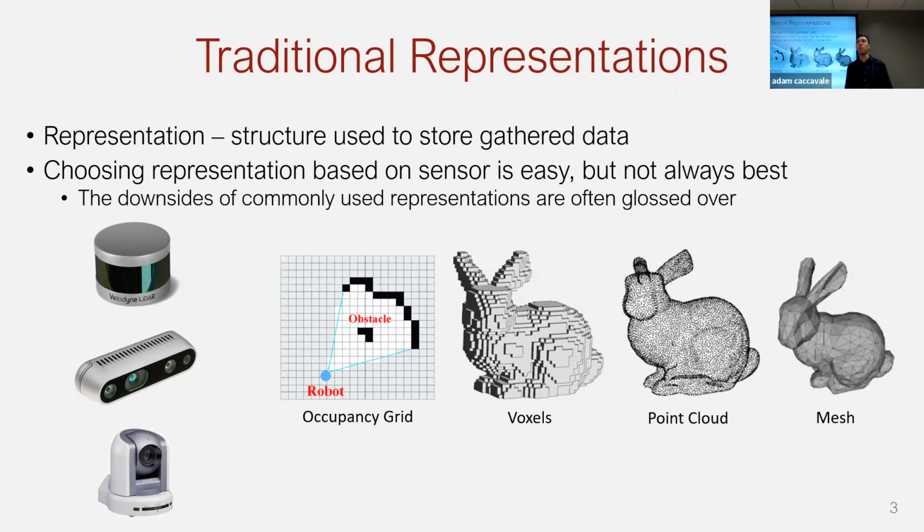You're probably familiar with the camera, and a depth camera is a cross between a camera and a LiDAR. So at each pixel, you get the color, but you also get the distance to the surface of the object. With this point cloud representation, it's very convenient to quickly build up iterative measurements because you can basically just overlay the point clouds, which is just appending to this list of X, Y, Z points.